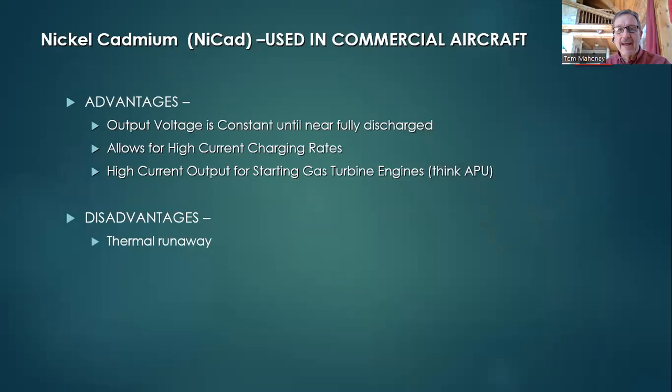Nickel cadmium (NiCad) batteries used in commercial aircraft. Well, why are we using NiCad batteries on commercial aircraft? Well, there's three big advantages. Output voltage is constant until nearly fully discharged. We'll take a look at that here in a second. It allows for a high current charging rate, so we can charge it rather rapidly.